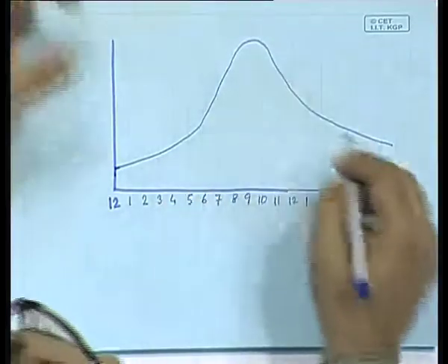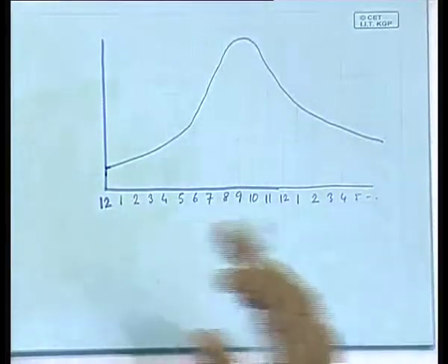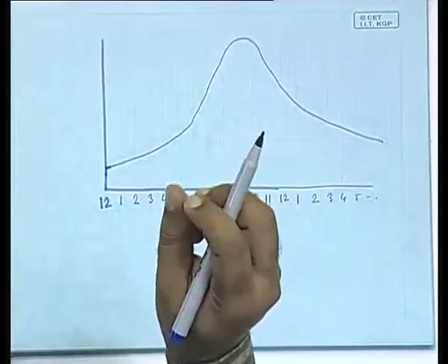It may not be exactly like this though, because that varies from season to season, that varies from city to city, city or rural area, it depends on that. But what I am trying to point out is that the load is continuously varying, and there is a particular time normally that comes in the evening, like say 7 o'clock to 9 o'clock, prime time, when the load is the highest. There is a peak power, peak load necessary. So the whole power generation has to satisfy this varying power load.